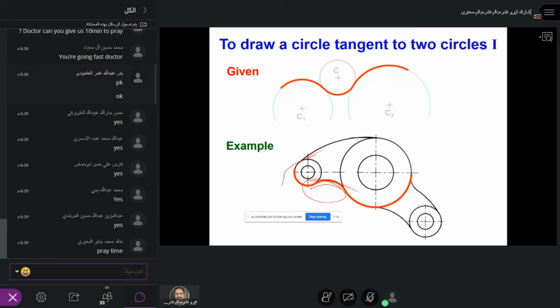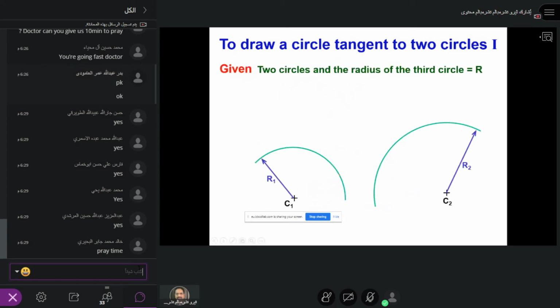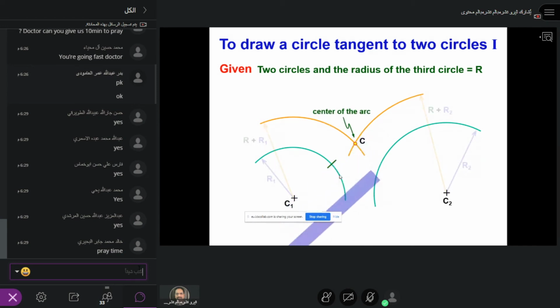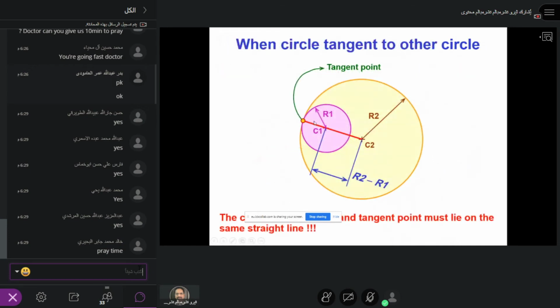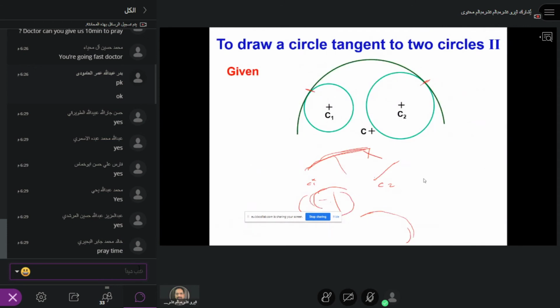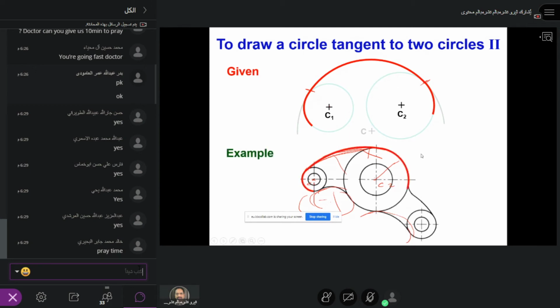But when you see this radius, these two circles are within the radius. So now you are using the plus here. Okay. So the first one is, since the tangent is outside, we're adding it. So that is done. Next one is inner, inside. So from the tangent point, the circle is inside, so you are using a negative, R2 minus R1. We did this. Now you see within that circle, this radius, these two circles are inside. So that's why you are subtracting it.